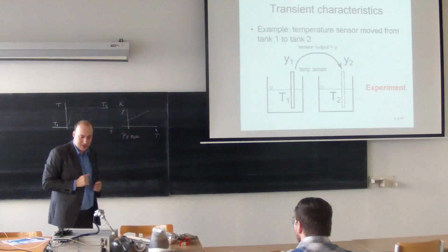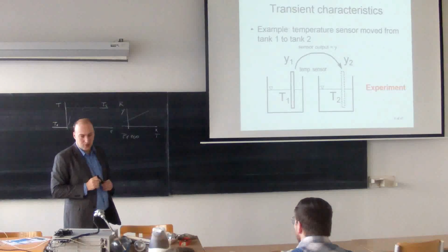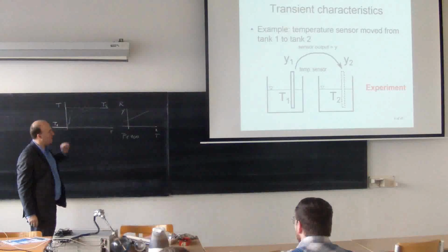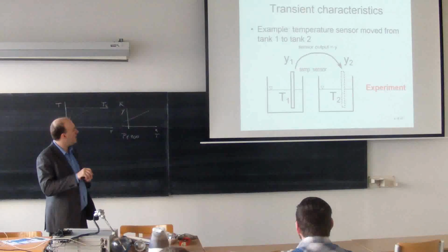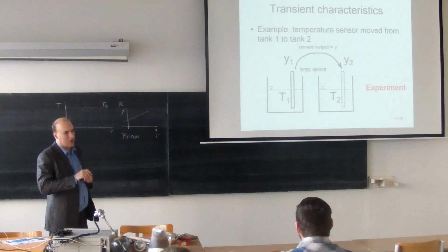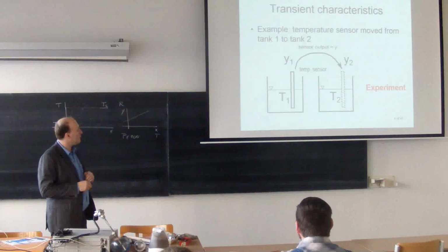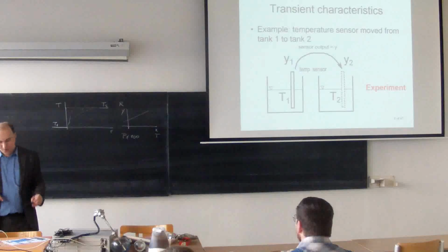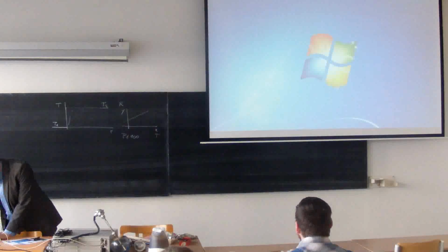Right now, the sensor is placed in the cold water, so that I have a constant temperature on the input. I will take this sensor and move it into hot water. We will watch the output of the sensor, and we will plot the response. So let's do it.